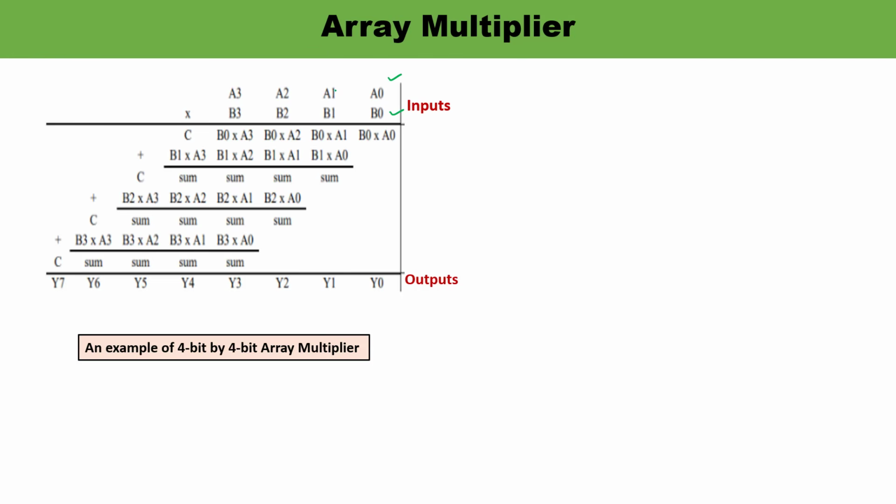See, multiply bit by bit. First you are going to multiply A0, A1, A2, A3 by B0. See, you are getting this stage. Then you will be shifting one position left and you will multiply with B1, A0, B0. In the next stage, you will be shifting one position again, right? This is how multiplication will be observed.